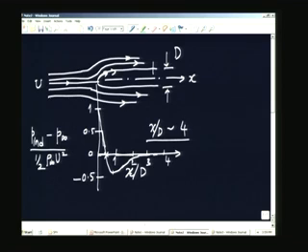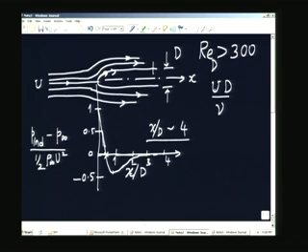Another 1 or 2 small points we will discuss. The second point is, let us look at the flow around this body. Some ideas from fluid mechanics we require, and I will just give the gist of the argument. If we assume that the fluid flow is taking place at a sufficiently high Reynolds number, Re, based on the diameter of the probe, Red will be nothing but u multiplied by d divided by nu, where u is the velocity, d is the diameter of the probe, and nu is the kinematic viscosity of the fluid which is flowing. If this is greater than 500, the boundary layer is very thin.